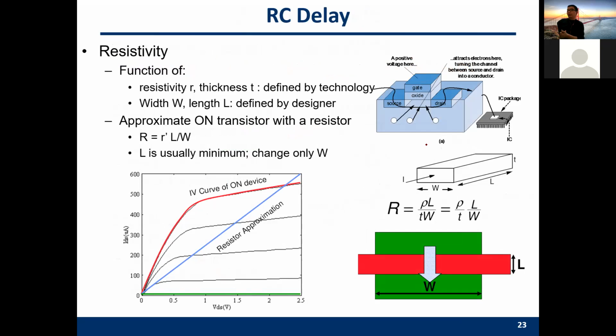So when we do homework one, we do not need to consider anything about the gates. The gates are ideal, are perfect for us. But when you consider the real physical gates, you have to consider the resistance and the capacitance of the gates. These are important parameters which can generate heat, consume power, and introduce extra RC delay, extra latency.